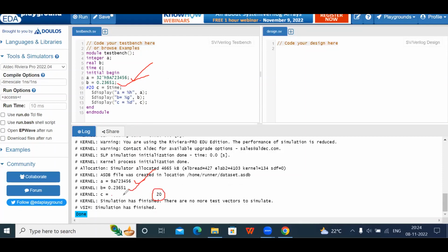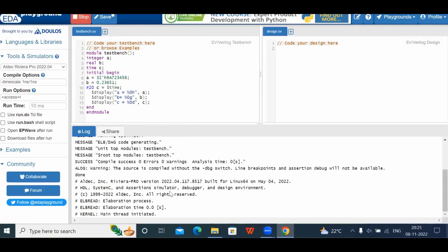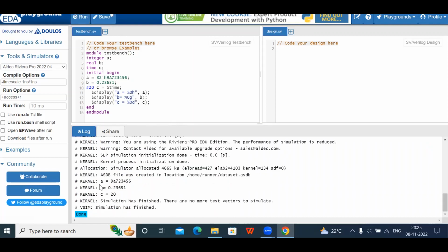See here there is a larger distance. You can minimize this distance whenever you get output like this, by simply putting a width here, the size width. Just 0 I am taking, which means minimum width. You can take 1, 2, or 4, whatever value based on the distance you want. See, now we got all values in order.